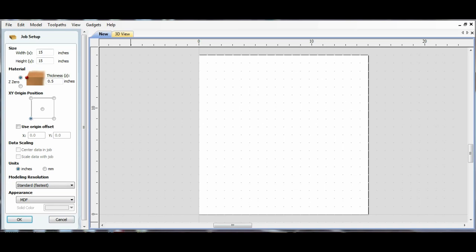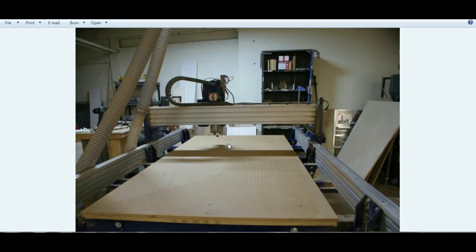And if you don't understand, let's go back to my picture, which is I think down here, of our machine. The farthest X, Y, Z, 0 position is going to be in this corner right over here. That's the farthest XY. You can tell the machine, which I'll show you, we're actually not going to zero when I put my part up there. I'm going to zero it somewhere inside of it.